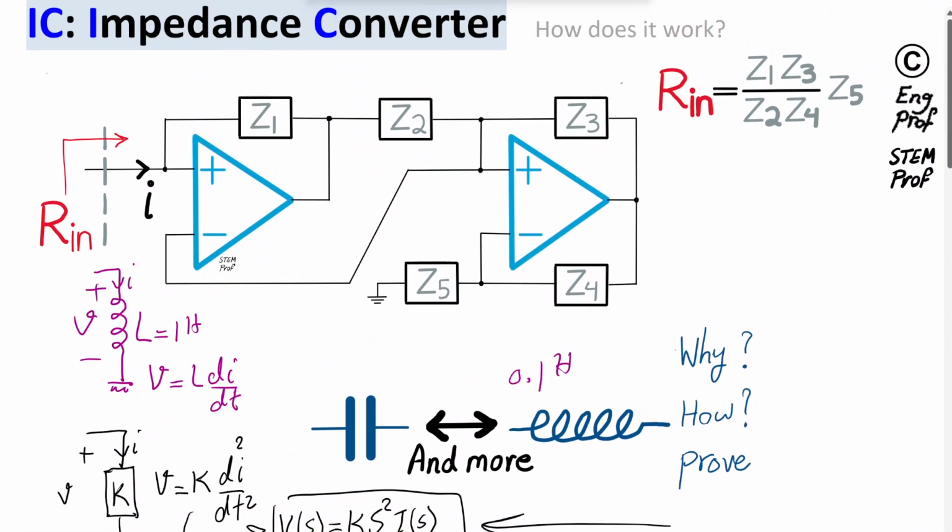You can see that effectively the wiring of the op-amp is such that, with proper selection of components, we have dominant negative feedback. So let's say, for example, this node voltage goes up suddenly. As a result of that voltage going up, the op-amp senses the input positive voltage, let's say the op-amp is already at steady state, but then suddenly the voltage at the positive terminal goes up. As a result of that jump, assuming the op-amp supply is connected, the output, noticing that the positive terminal is jumping up, would increase toward the maximum supply voltage.